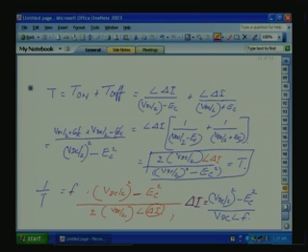If you see, if you want high frequency PWM, that means F is more, then delta I will be very small. For frequency to be reduced, if we do not want high frequency PWM, then delta I will increase. The moment delta I increases, the current ripple amplitude will increase.